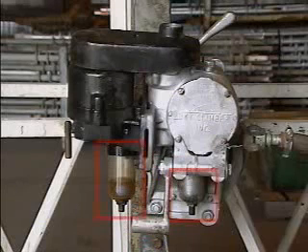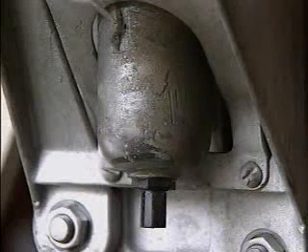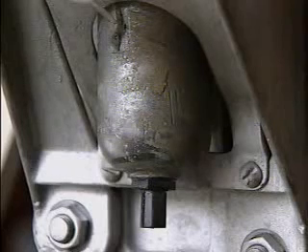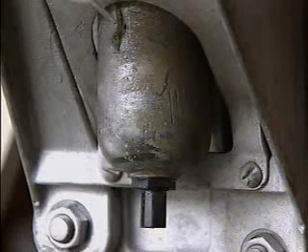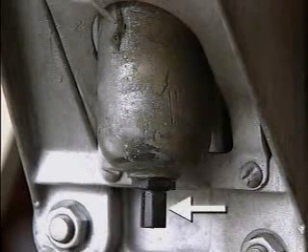The airline oil system has two vessels. One vessel is the oil reservoir. It displays the oil level in the system. The other vessel is a condensation trap. It removes moisture that could corrode components in the air system. Before the scaffold is used, the moisture should be drained from the vessel by depressing a valve stem in the bottom of the vessel.